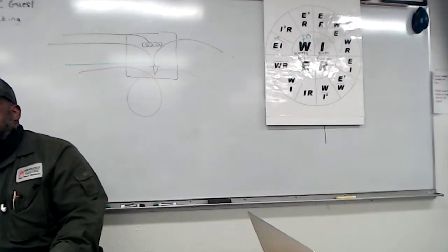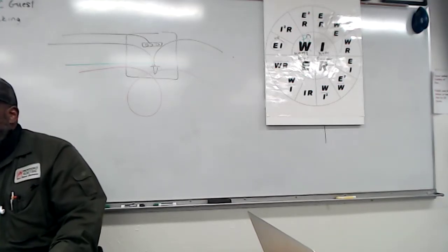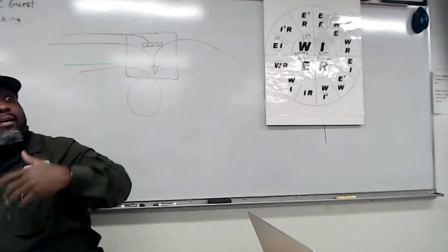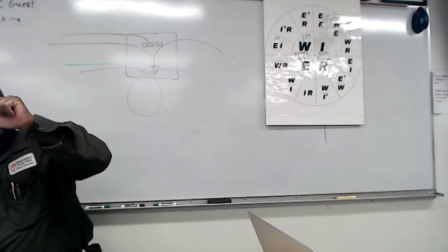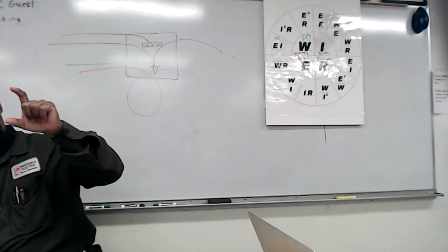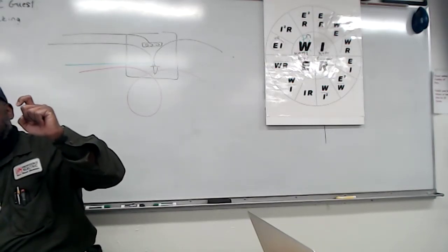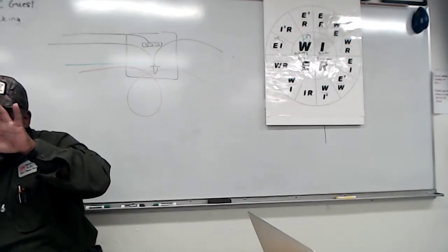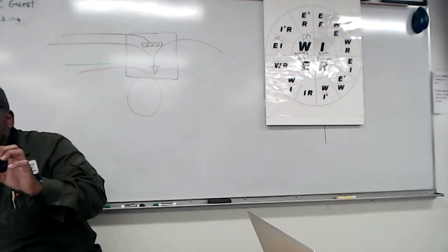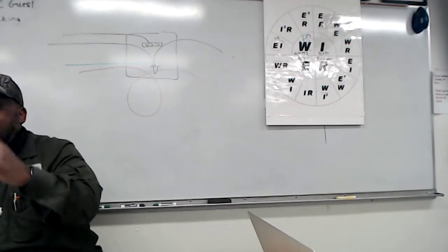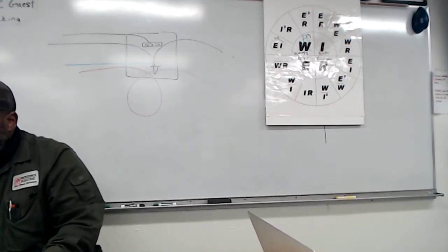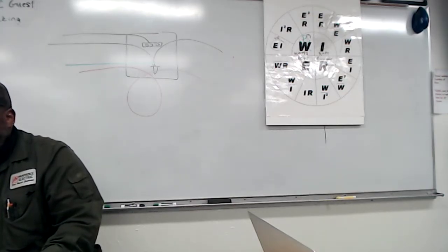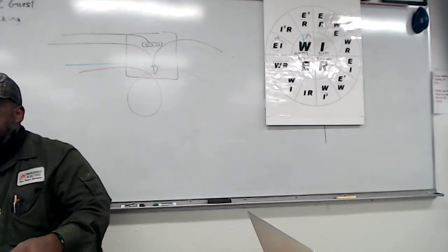So basically, a receptacle is 2 allowances. Yes, receptacle, GFI, anything that is on a yoke. The yoke is the part you use to screw the device into the box. That little piece you be screwing into, that 6-32 screw, that's a yoke. It gets 2 allowances based on the largest conductor that's actually attached to that device. Not that's in the box, that's attached to that device.